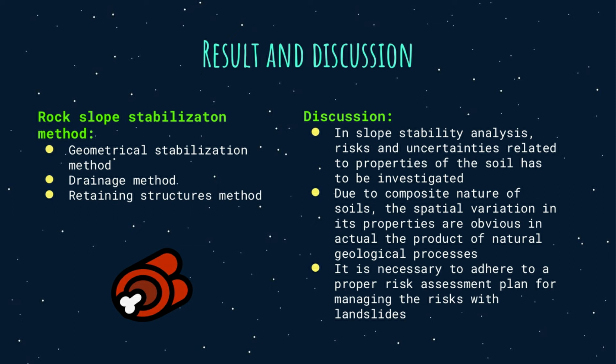As we can see, this retaining structure includes gravity retaining walls, cantilever walls, contiguous bored pile, caisson, and steel sheet pile. If the driving forces are too great to resist, ground anchors or other tie-back systems may be utilized in conjunction with the retaining structure.